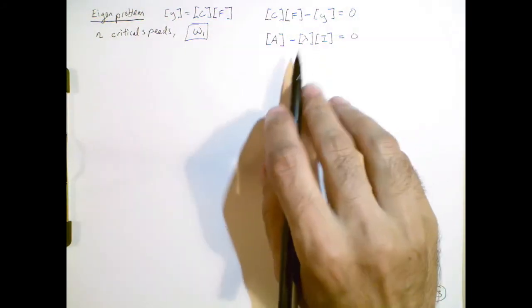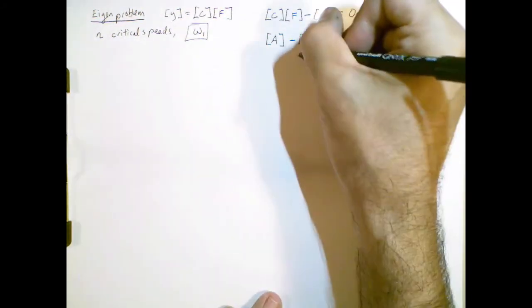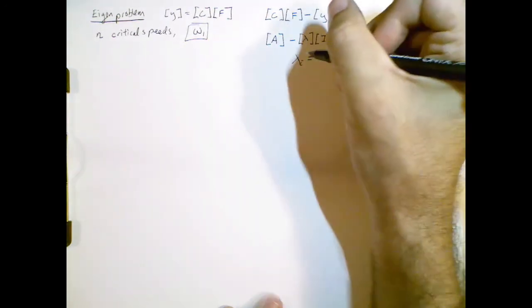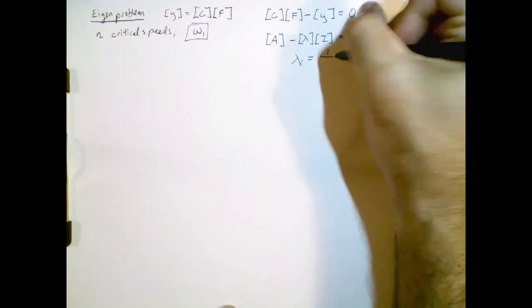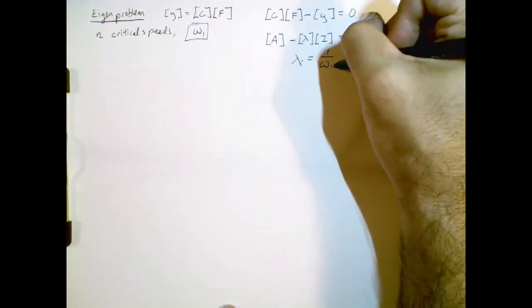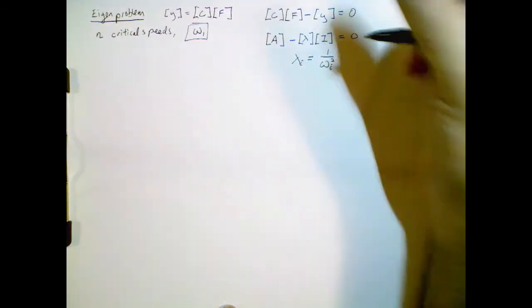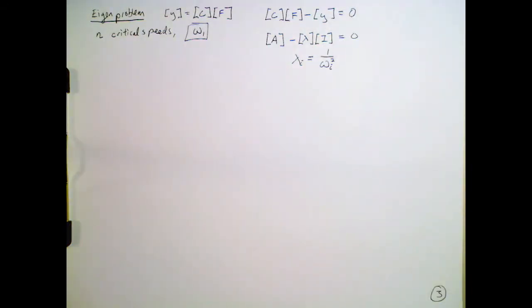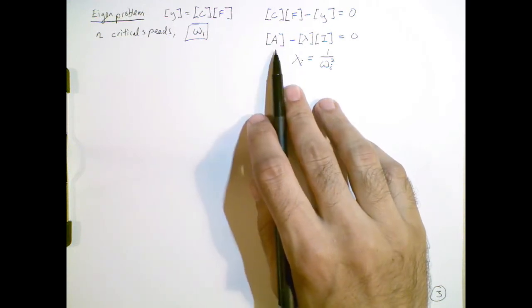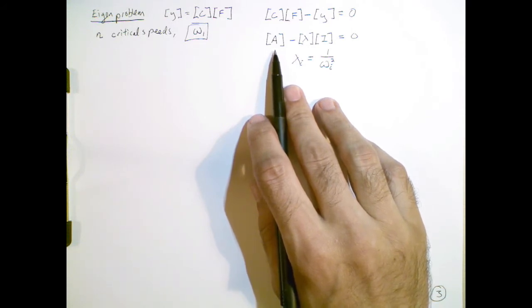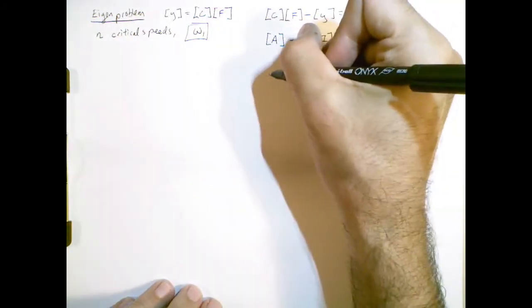So this vector we're going to define as one where the ith element of that vector is equal to 1 over the square of the ith critical speed. It's possible to derive this matrix, and in your textbook it goes through a simple n equals 3 system and works out the equations for this. But it's possible to simply write out this matrix using this formula.